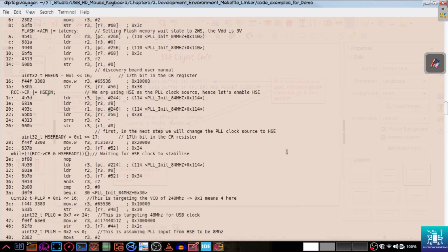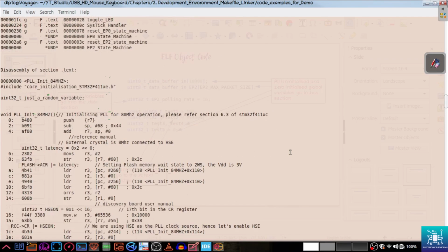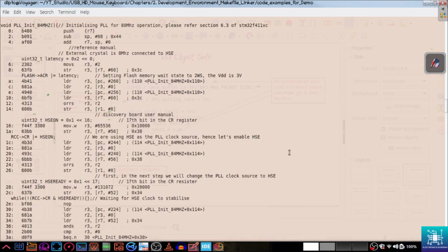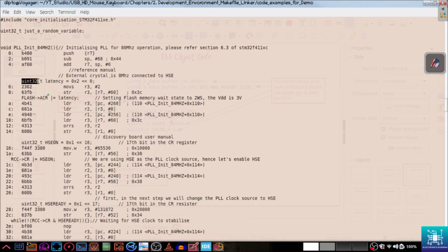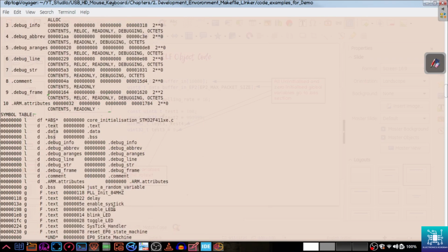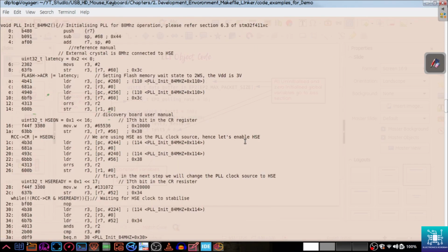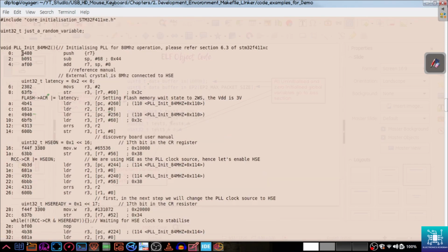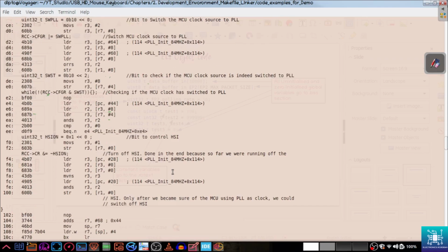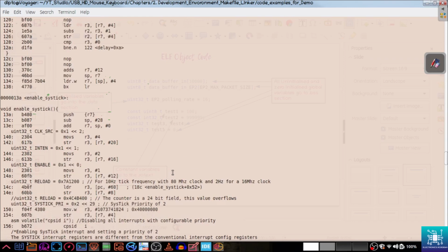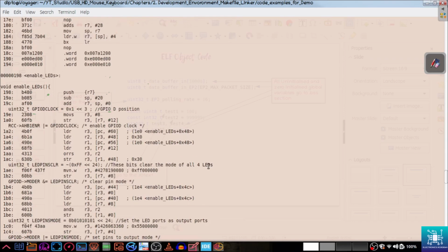But when we are flashing this object file onto the board, all this information goes away. We will have to do an objcopy, and all of this, the information about the symbol table and sections and so on, all of it goes away, and what is copied is only this part, the machine instructions. Nothing else stays. So .text and .data go in, with only the binary.